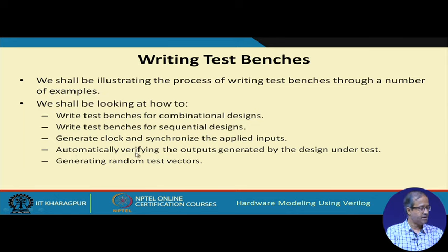And also we shall talk about how we can automatically verify the output generated. For example, let us say I am designing an adder. My test bench should be such that it applies the inputs, reads out the output, and automatically compares whether the output is coming correctly or not, and just tells me that the design is good or bad. So, it will not just show me a list of all the inputs and outputs, it can also tell me whether the output is coming as per the specification or not.